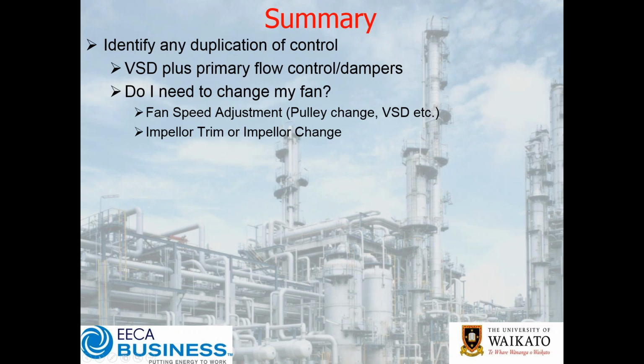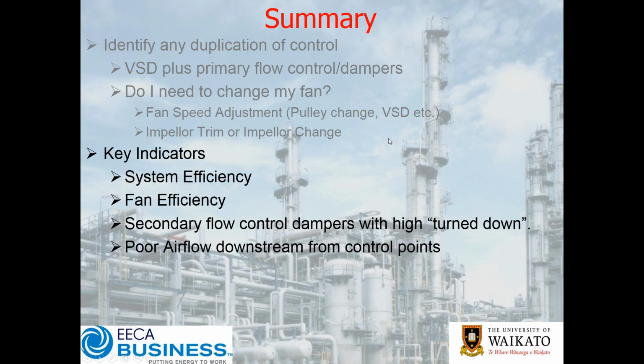So in summary, to finish off today, you want to identify any duplication of control. Where you've got VSDs plus other primary or secondary control dampers, have a close, hard look at that. Are they all necessary? Can we get some improvements by rationalizing them? Do I need to change my fan? Is my fan too big? Is it a pulley change? Is it a VSD, or do I need to actually look at my impeller?